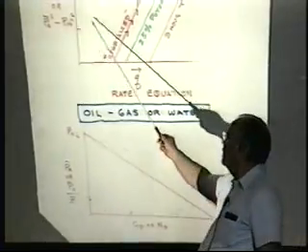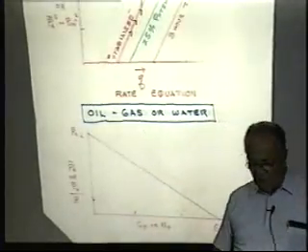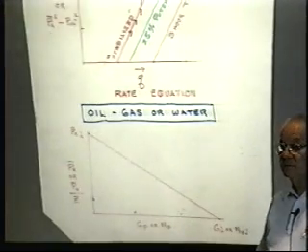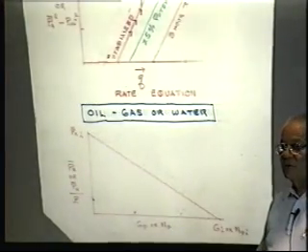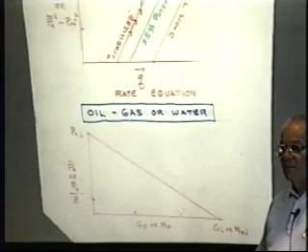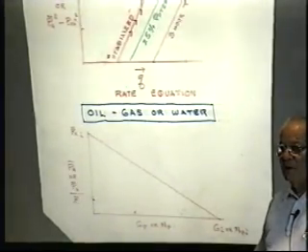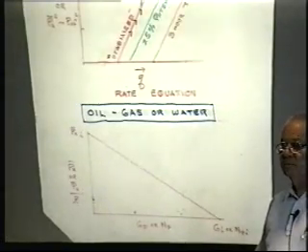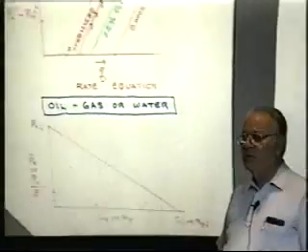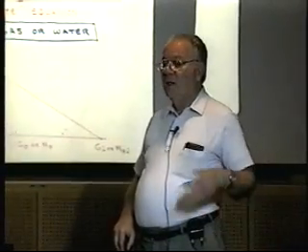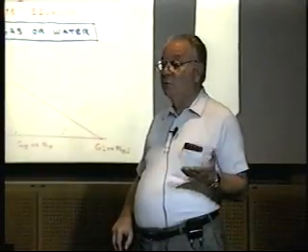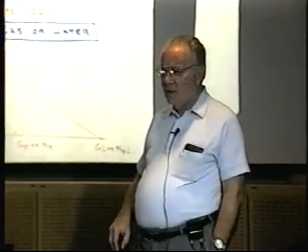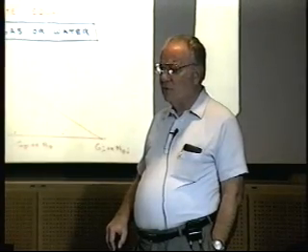We've demonstrated with our isochronal testing of oil wells that for your solution gas drive reservoir performance, behavior down in that region is a function of a difference in pressure squared. Above the bubble point, it would be delta P. Single phase water flow would be delta P. A lot of people use inflow, and there are a lot of programs out there that use Vogel's equations for inflow performance. And several also use Vogel's equation for water flow.